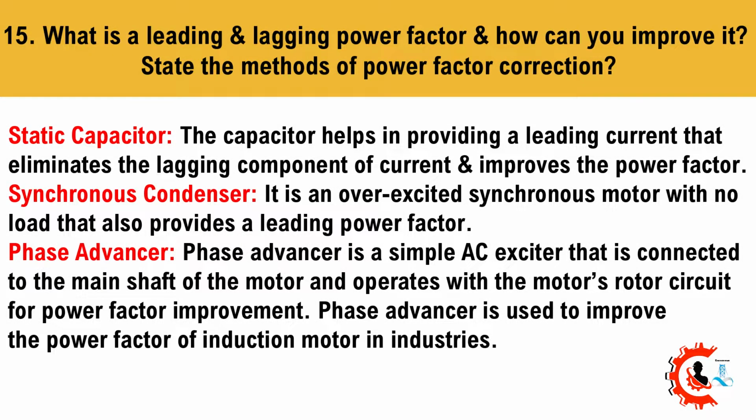Static capacitor. The capacitor helps in providing a leading current that eliminates the lagging component of current and improves the power factor. Synchronous condenser. It is an overexcited synchronous motor with no load that also provides a leading power factor. Phase advancer. Phase advancer is a simple AC exciter that is connected to the main shaft of the motor and operates with the motor's rotor circuit for power factor improvement. Phase advancer is used to improve the power factor of induction motors in industries.